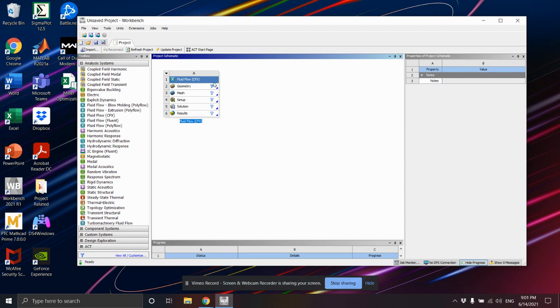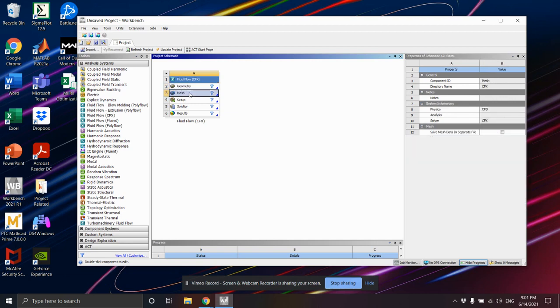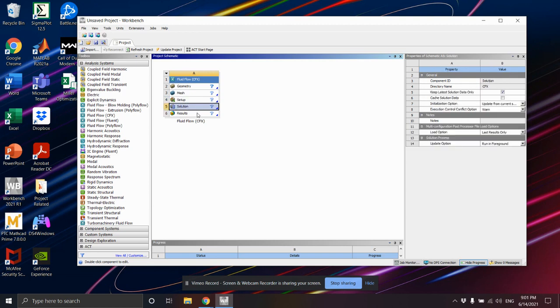First is the pre-processing, which will be setting up your geometry and setting up your boundary conditions, where your loads are, the material that you're using, everything that involves the setup. And from there on, you're gonna start producing some results. The last step would be to post process those results.